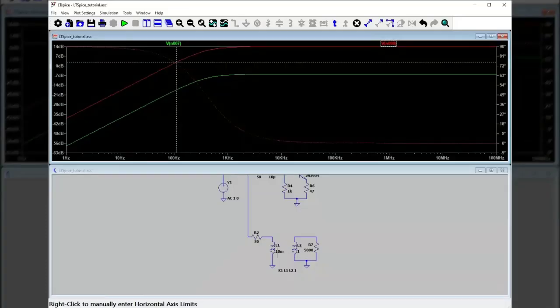Because we don't have these inductors big enough. And so if we wanted to extend this down to 100 hertz instead of a kilohertz, well, we could make both of these inductances 10 times as big. And if you wanted to go lower than that, you make them still bigger. And then maybe you can appreciate why 60 hertz transformers are so big, because they need big inductances. Because we're working at 60 hertz, right? So pretty low frequency. So that is it for this transformer.